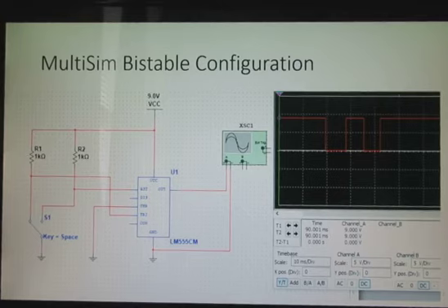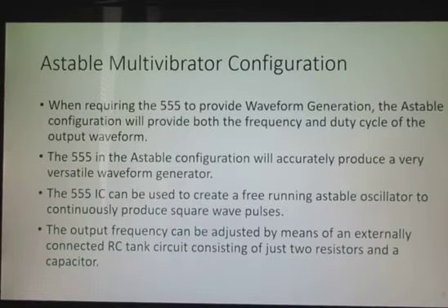So I did a Multisim setup of this circuit. Notice that the current state of the trigger input is grounded, causing the output to set high. And when I change the position of the switch to ground the reset pin, it goes low. That's all there is to it. Pretty simple. And so the switch could be a circuit giving a low or high as well.